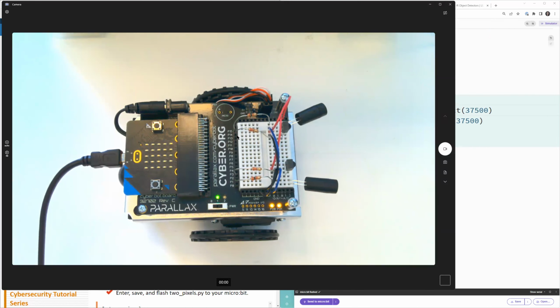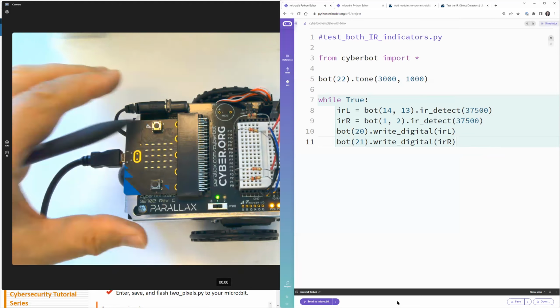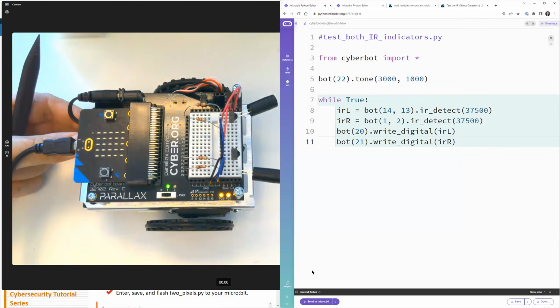The reply is, okay, so these numbers come from resistor locations and not the sensor location. What it's really doing is it's the number of the IO pin that is connected to the sensor, but it's connected through the resistor. So that's correct. It's the resistor that's completing the connection between the row that the sensor is plugged into and the IO pin.